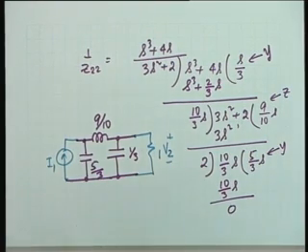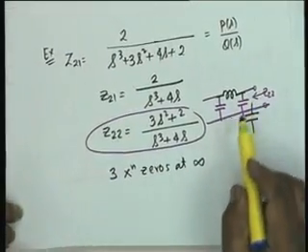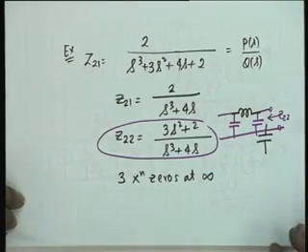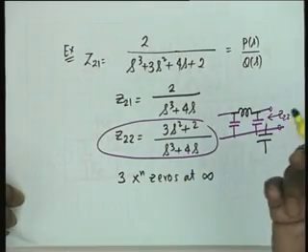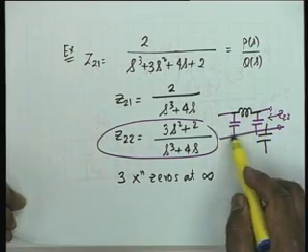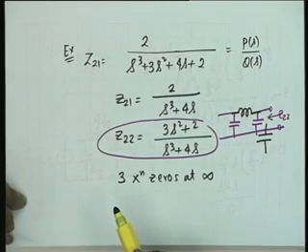So what will be Cauer 2? Cauer 2 concentrates on poles at the origin. The structure here is the structure dictated by the transmission zeros. I could have expanded Z22 in Cauer 2 or even Foster 1, Foster 2, no problem. But in order to realize transmission zeros at infinity, I do need this structure. I cannot do it with Cauer 1. I am sorry, Cauer 2. So the capacitors could have been on the other side of the circuit. Capacitors could have been what? Exchange.